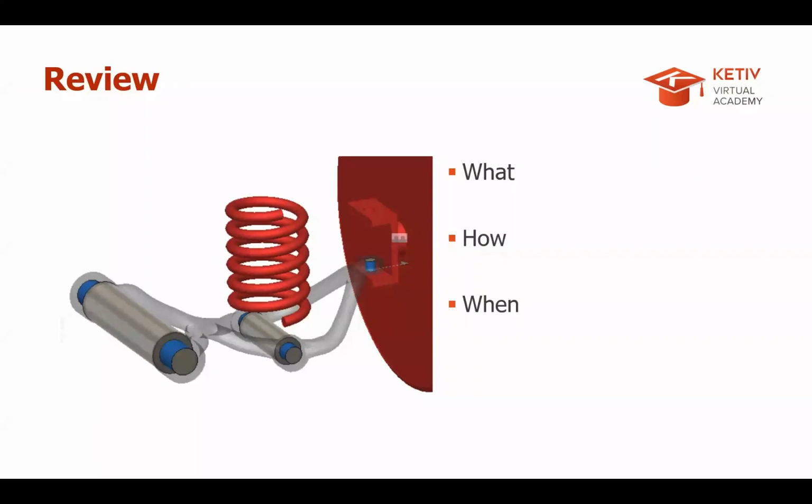Okay, so just a bit of a review of what we covered. We covered the automated modeling tool. It's one of Fusion's new preview features that you're able to enable within your Fusion. How it works differently as opposed to the generative design tool, and how you can use it to start some of your projects or parts, and when you could use it and how you can avoid some issues with it, maybe avoiding some parts or some spaces where you don't want it to create geometry, and how you can go back and edit it and leverage this. So within Fusion, how you can use it to also switch into the simulation tab and run your simulation, and maybe go back and edit some of the solids that you create with this tool.